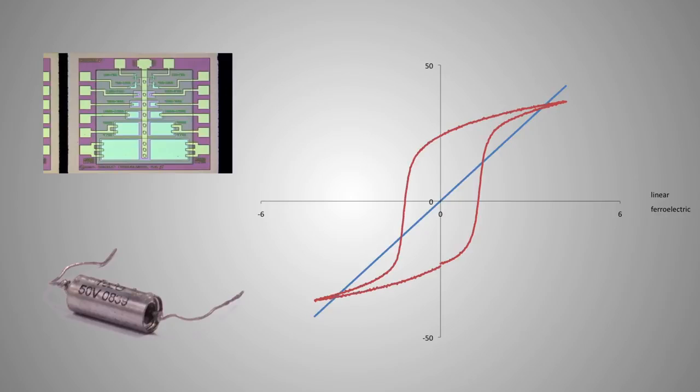Why do we want to plot the capacitors in this way? Linear capacitors can be defined by a single number, the slope of the line they make on the plot. Nonlinear capacitors, on the other hand, have curvature. They cannot easily be defined mathematically, so we plot them instead.